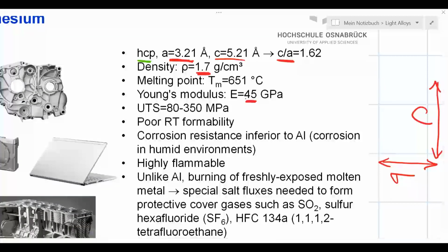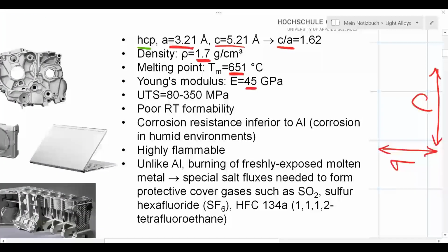And also in terms of temperature capabilities, if you have a thermoplastic polymer, you take it to 100 degrees Celsius, you could assume that it loses strength dramatically. Right? So the stiffness goes down, it goes much below 1 gigapascal, and the capacity to carry a load decreases a lot. With magnesium, we got a melting point very close to that of aluminum, only about 10 degrees lower than aluminum. It makes it easier to cast magnesium alloys.